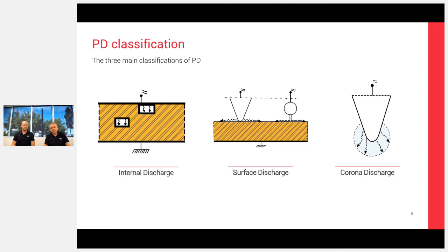However, with modern, more air insulated switchgear, you get a bigger chance of surface discharge happening on air insulated components. The third type of discharge is corona discharge. We see this more on a sharp point into a gas, and often you'll get that in the open terminal switch yards. Not a massive issue unless you have the corona discharge happening inside, say, an air insulated chamber which